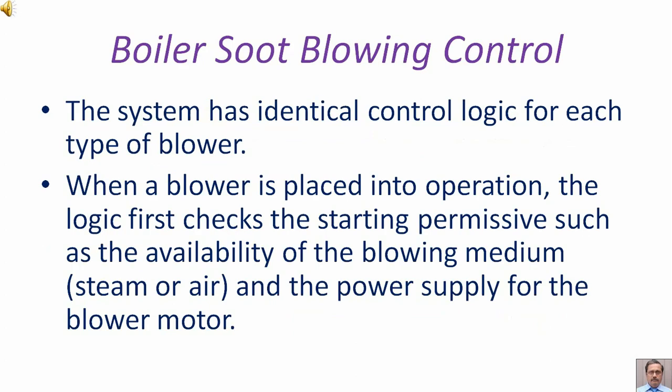The system has identical control logic for each type of blower. When a blower is placed into operation, the logic first checks the starting permissive, such as the availability of the blowing medium, it may be steam or air, and the power supply for the blower motor.